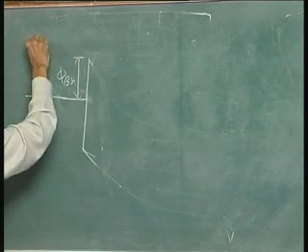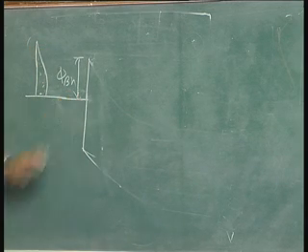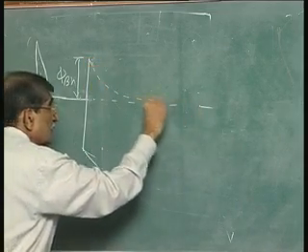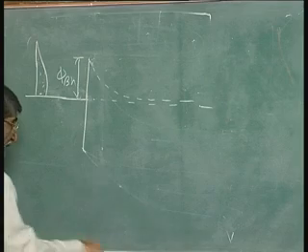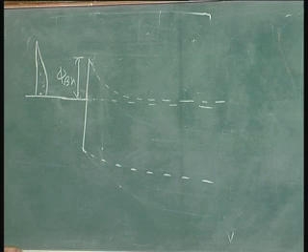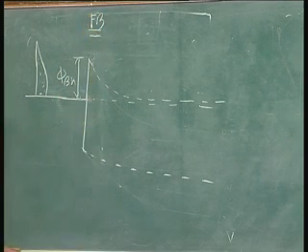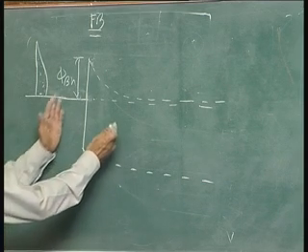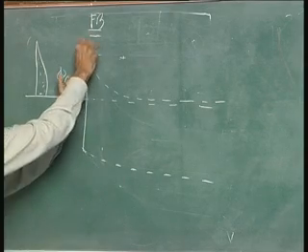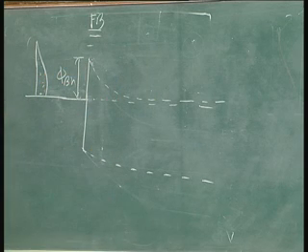You have here this barrier. Whatever you do, that side is not changing. So, at thermal equilibrium, you had the situation where the Fermi level was here and you have the energy band diagram like this. Okay. That is thermal equilibrium. I am putting a dotted line because when you forward bias, whatever barrier was there having a potential plus minus, if I apply plus minus there, like what you have done in the forward bias, you are reducing the potential across the device.